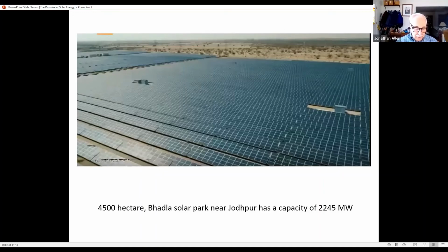For all its green advantages, solar power is intermittent. We've hinted at that before, both in our diurnal cycle and as a function of weather. In the continental US, a fixed latitude tilt panel gets between 3 and 7 sun hours a day, 4.5 in New Jersey. During the off hours, the grid needs other sources. Wind, which is the other main green energy, is also variable. So we need some baseline. Nuclear is an option, but energy storage would certainly contribute a lot.